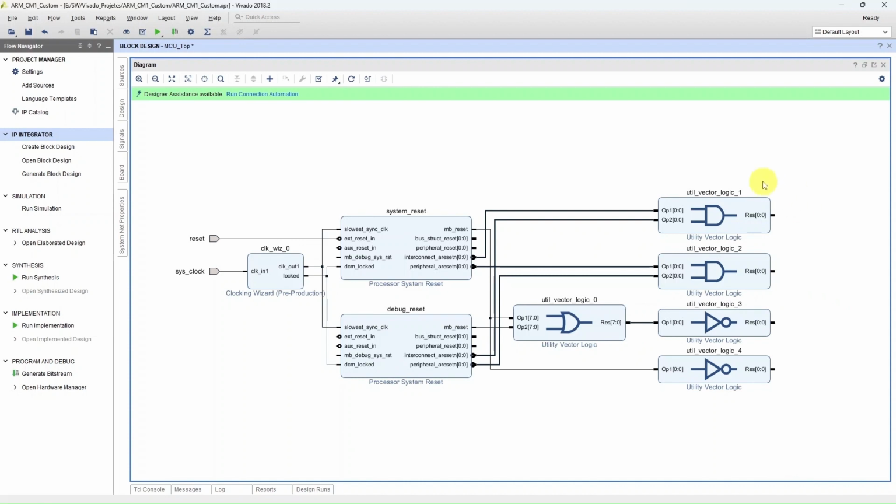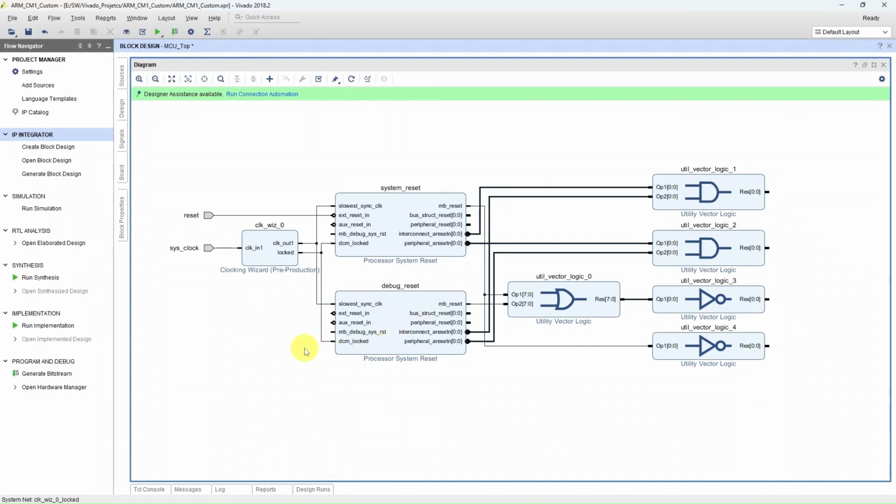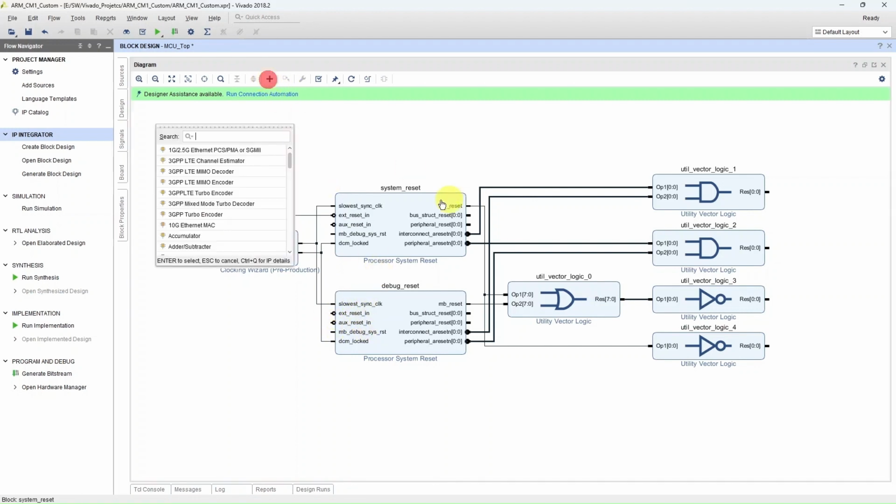So we finally have 4 reset signals coming. This is for the interconnect reset combined. This is for the peripheral reset combined. This is for the system reset N, sys reset N, and this is for the debug reset N. The 2 signals, external reset N and the auxiliary reset N, for the system reset request, we cannot leave them hanging. So we'll just pull them high because these are active low signals, so that they'll forever remain deactivated. We'll just search for constant.